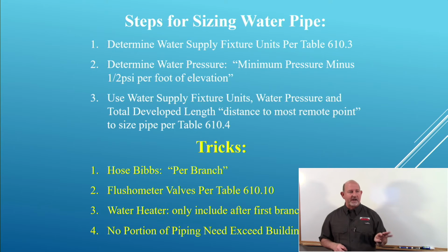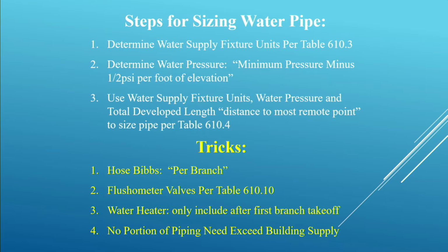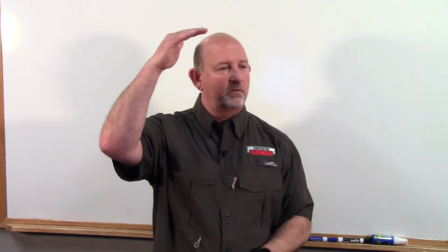Number 3 and 4 kind of go hand in hand. Number 3, water heaters only include after the first branch takeoff. Water heaters do not consume water. Water heaters don't drink water. All water heaters do is bring water, store it, heat it, and distribute it out, right? So do you agree? Once that tank and that water heater is full, it'll never consume water ever again, okay? It'll only pass water through there.